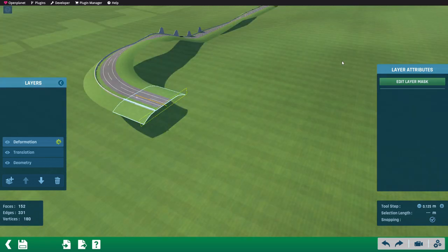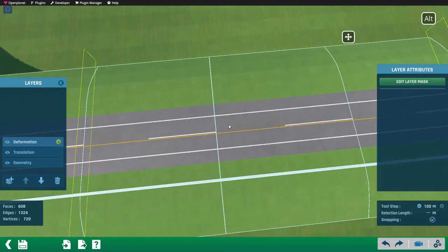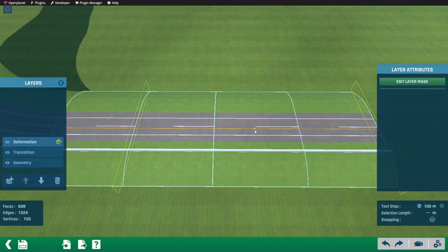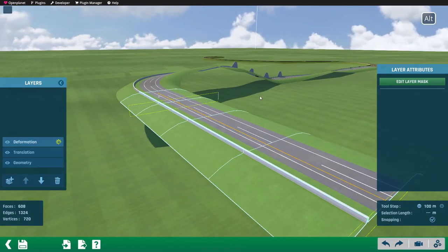Number 6. Another thing to know is that applying a deformation somewhat compresses the geometry. At the position of control frames the geometry will be exactly the right one, but not in between. This is irrelevant for most use cases, but it can be a problem for specific cases like partitioning a geometry after a deformation. It is just something to keep in mind.